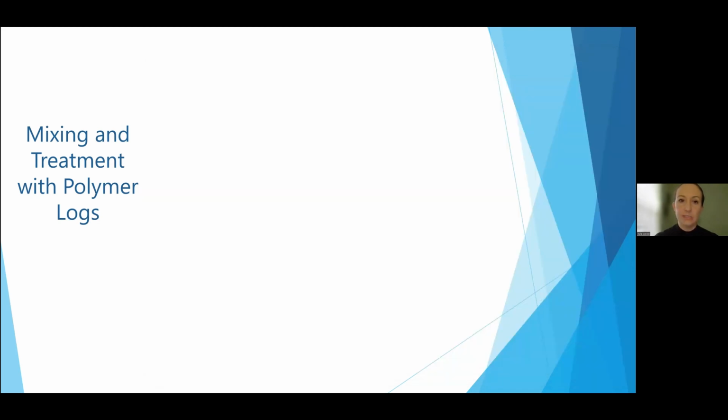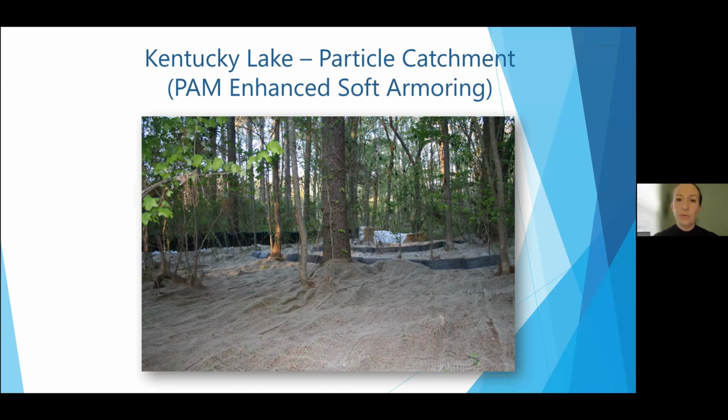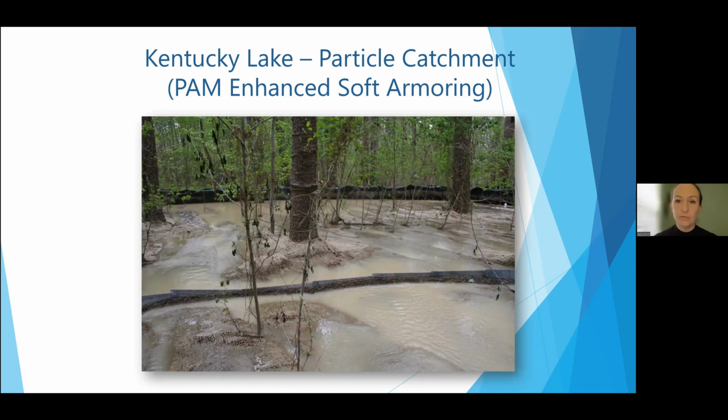So this was our mixing system. The forested area, again, we lined it with that jute matting. We're hoping, and we added some polymer at the front end of that, to get some more reaction and also to start collecting those flocculated particles. You can see they also added some baffles to help slow the flow down, get some more mixing and reaction. Again, the more mixing and reaction we can get, the better the results are going to be in forming those flocks. So we have the water that's flowing over them, forming those flocks. It's starting to collect on the jute matting.